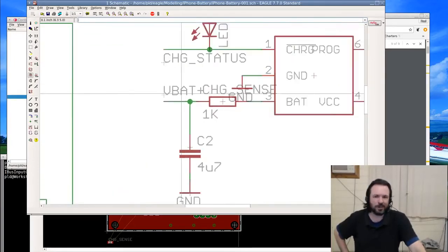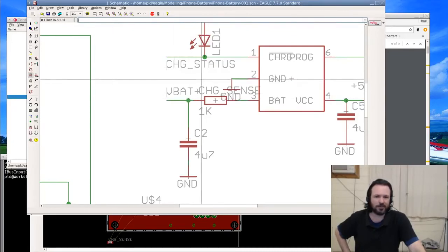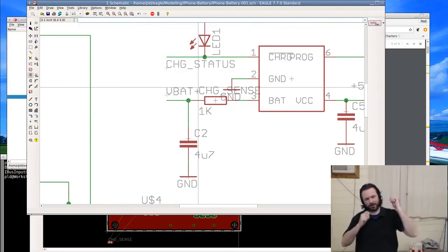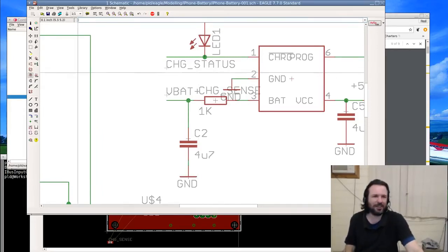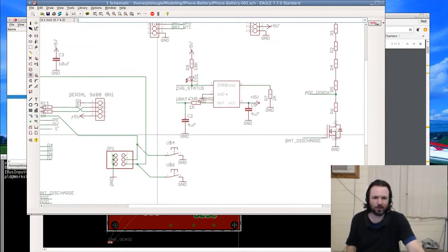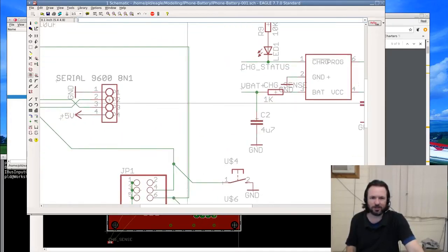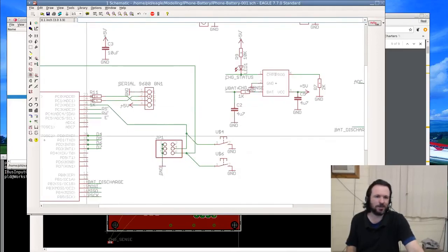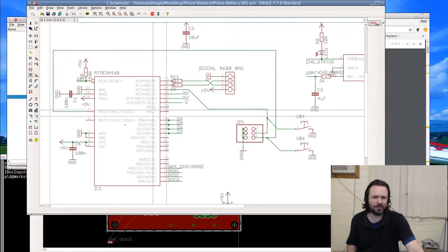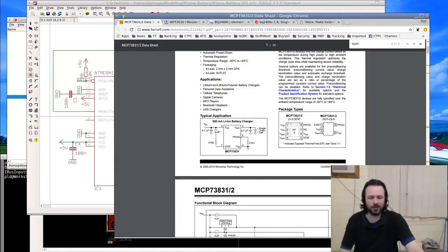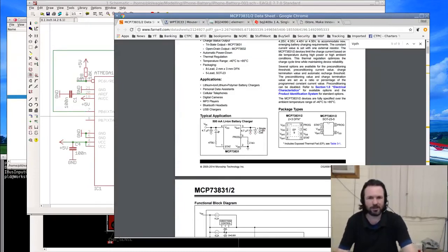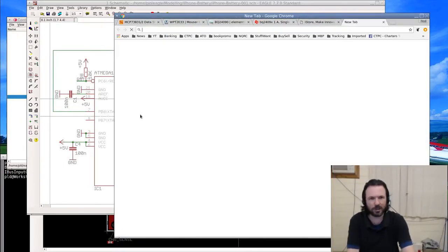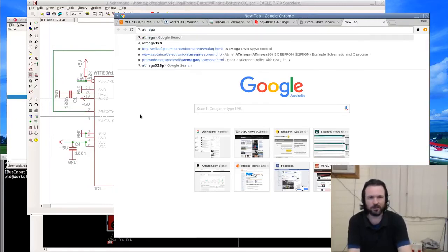Yeah, Spencer, high side current sense, because I need to be able to coulomb count how much is going into that battery. I could put a proper coulomb counter chip in there. I've used them before, but it's a lot of money for, I don't want it that accurate. I'll be happy within 10% for what we're doing here. So I may just have to use 2 ADC lines, since I don't think I've got differential. Oh wait, maybe the new ones do. Do the new AVR Mega 8 series have differential ADC? There's a Mega 88. Okay.